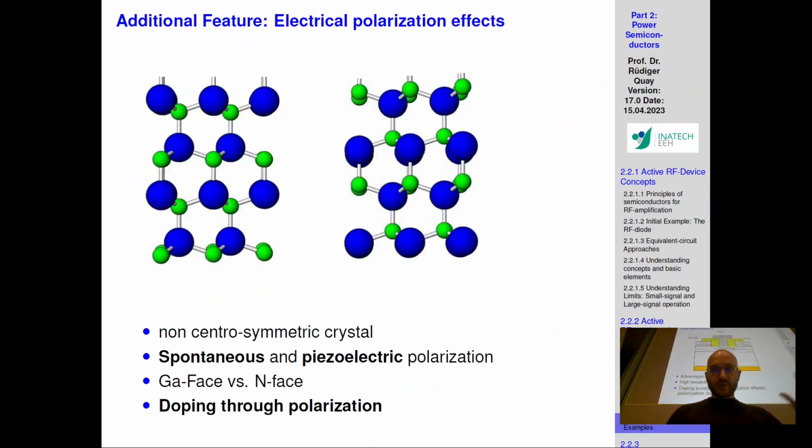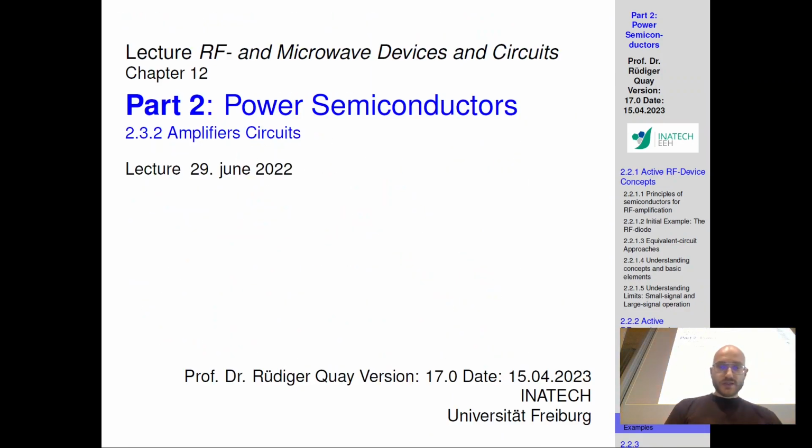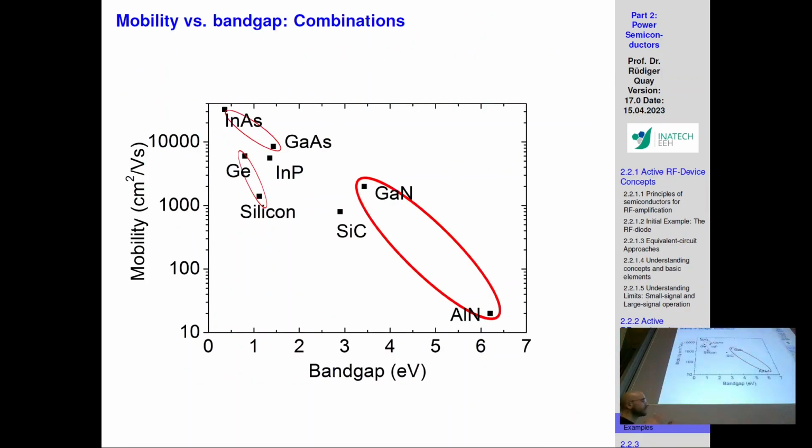Yeah, move a little bit back, because we discussed this: for power semiconductors, we can no longer stick with silicon. Silicon has a small band gap. What does a small band gap cause? We cannot apply high drain-source voltages, or emitter-collector bias. Because you cannot sustain large electric fields in the device, you might have a device that just burns out, we need a larger band gap.